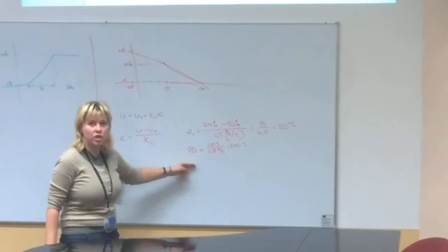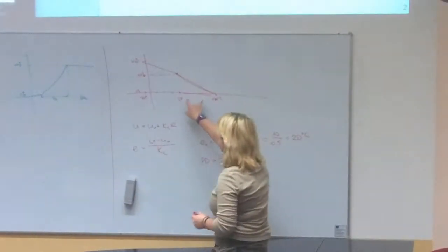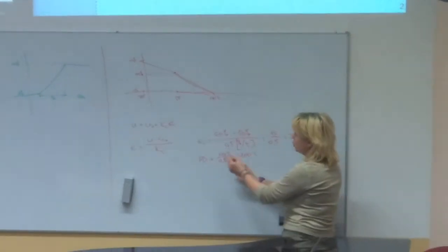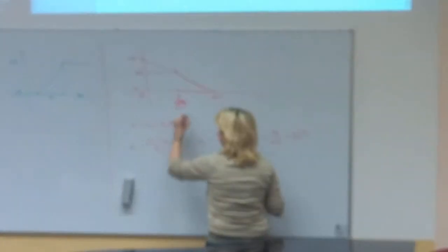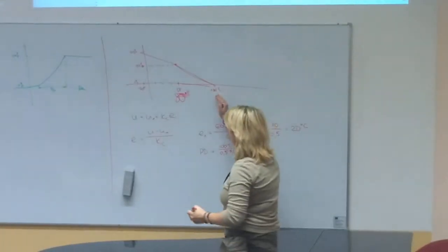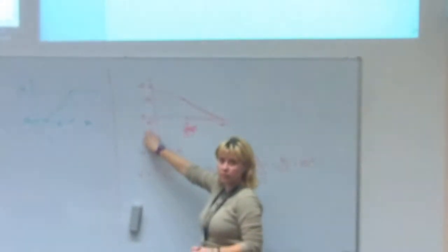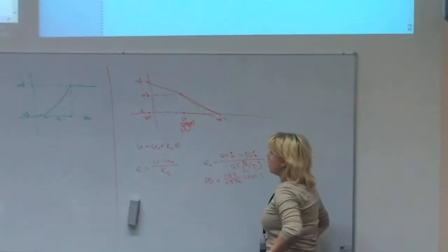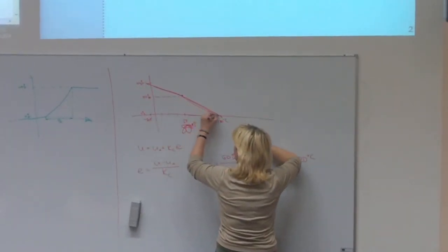So having such a huge proportional band, basically I just divide it by 2. Because our set point equals 80 degrees Celsius, I just add 100 here and subtract 100 from here. And that means that our characteristic is like that.